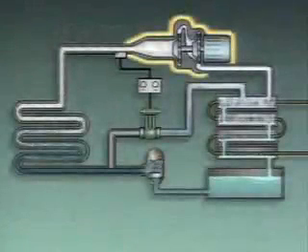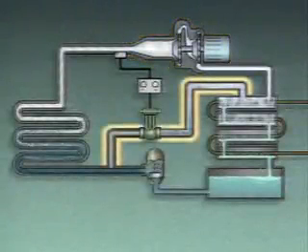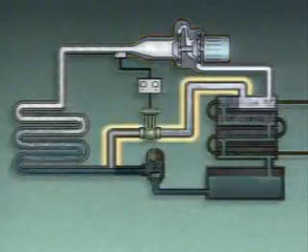In systems with centrifugal compressors, the compressor runs continuously, and there may be additional components to maintain the desired values. For example, in this system, a bypass line routes some of the refrigerant around part of the condenser, the receiver, and the expansion valve.